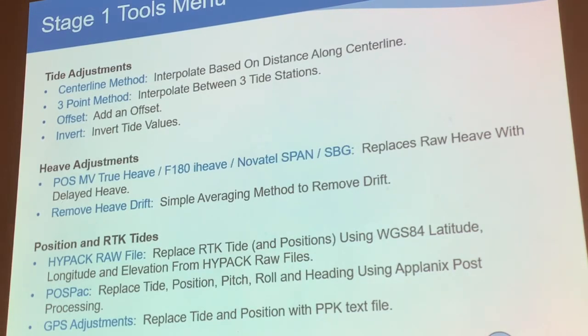Will the sound velocity change or not? No, okay, the sound velocity usually will only change between fresh water and salt water. And also when you go from shallow water to deep water, the sound velocity will change. But usually the sound velocity, like when you see single beam, will be from 1480 to 1530. 1530 is about very salty water. 1480 is very fresh water.